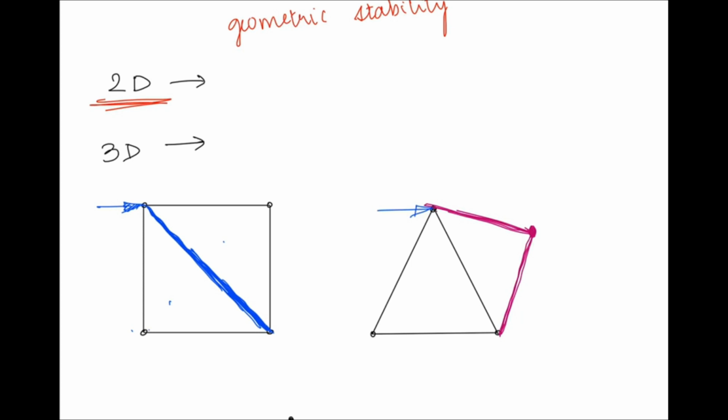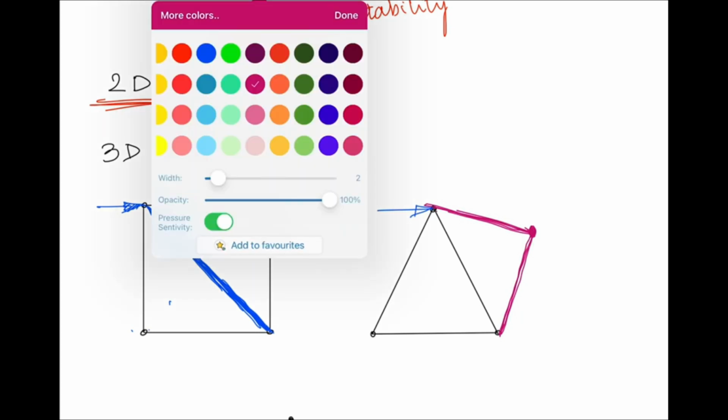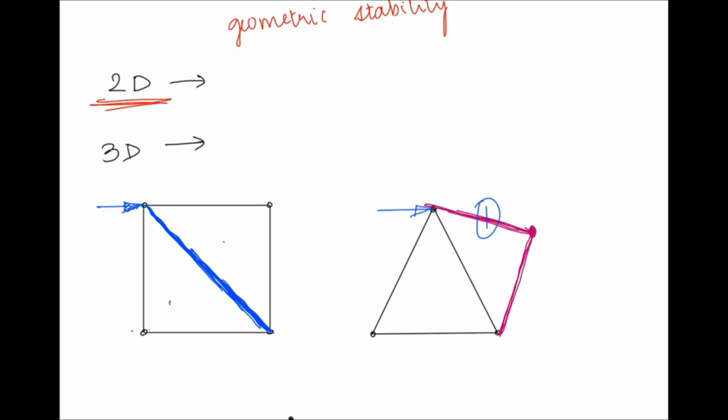Okay, so for every joint you require two members, one and two. So that's why the equation will be the minimum number of members to maintain geometric stability: two members per joint, so 2j minus, now you see here you have the extra number of members. So how many extra members do you have? 1, 2 and 3. So you subtract 3 from there.